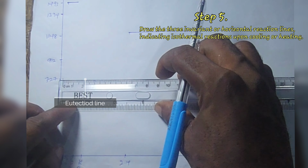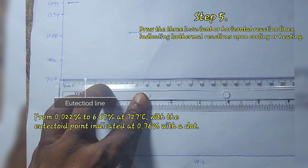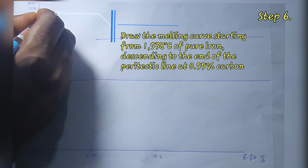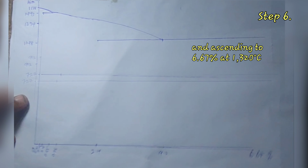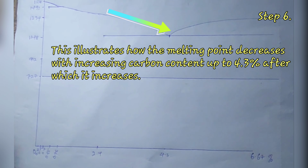3. Eutectoid line. From 0.022% to 6.67% at 727 degrees Celsius, with the eutectoid point indicated at 0.76% with a dot. Step 6. Draw the melting curve starting from 1538 degrees Celsius of pure iron, descending to the end of the peritectic line at 0.55% carbon, then to 4.3% at 1148 degrees Celsius of eutectic point, and ascending to 6.67% at 1320 degrees Celsius. This illustrates how the melting point decreases with increasing carbon content up to 4.3%, after which it increases.